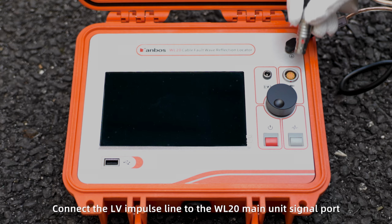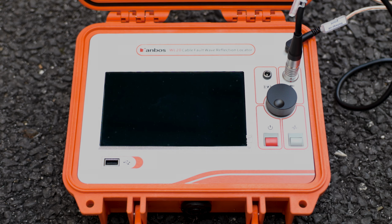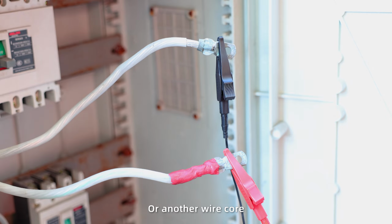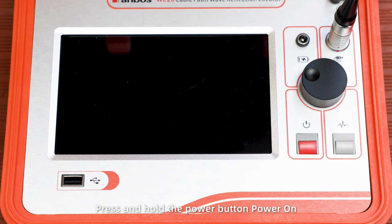Connect the LV impulse line to the WL20 main unit signal port. Connect the red clip to the core wire. Connect the black clip to the ground wire, or another core wire. Press and hold the power button. Power on.